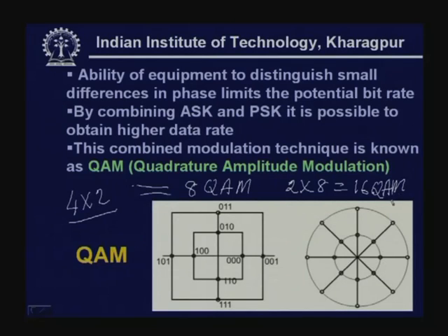So we find that for each signal element there is change in phase or frequency. That means you can have 2 different amplitudes and 8 different phases, leading to 4 bits to be sent per signal element. So we can see you can send at higher data rates. So this is the 16 QAM.